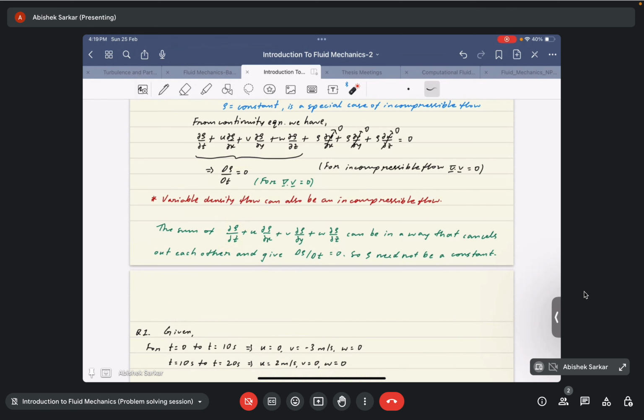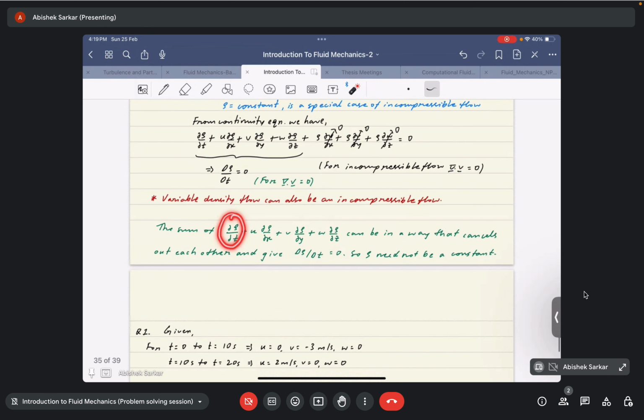And it might happen that even if this is not 0, these terms can have values in a way that the net sum of this expression can be 0. Even if these terms are not individually 0, the values of the individual terms can be in such a manner that the net sum of all these expressions is 0, which will again correspond to d rho by dt being equal to 0, but it does not mean that rho is equal to constant.